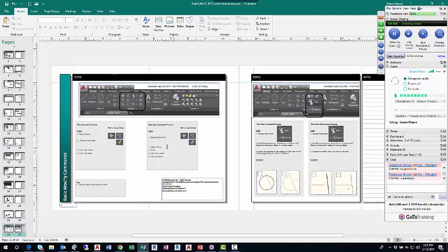The method on the left is the user selects the object to be modified, like the line, a circle, or whatever, and then selects the command. In the case of the erase command, once you've selected the erase button, the command is over. In the example of copy and move, the command prompts will walk you through the evolution of that command. So when possible, I like to select the object first, then the command after.